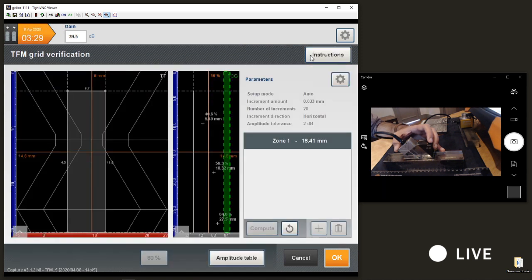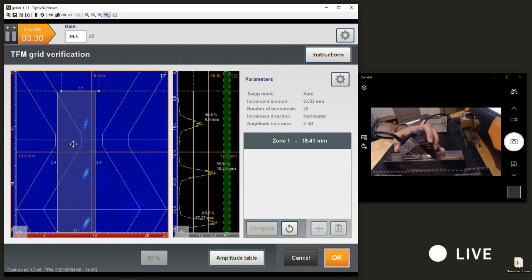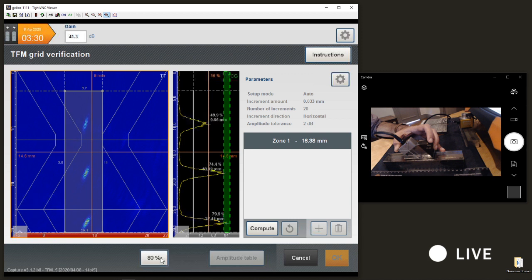This is the Amplitude Fidelity. The way we have implemented it is essentially what the ISO standard, which is going to be published later this year, describes. We have our holes right here. We are just going to position an area to make sure that we are capturing the amplitude of the 3 holes. You have the echo dynamic right here with 1, 2, 3 amplitudes. I'm going to reset it because I calculated it before.